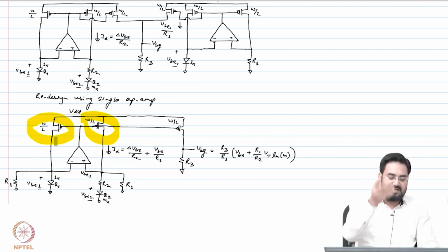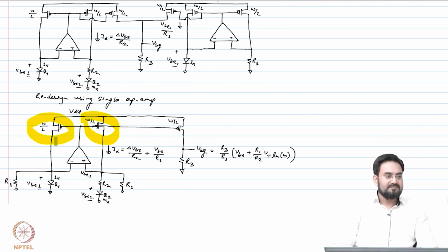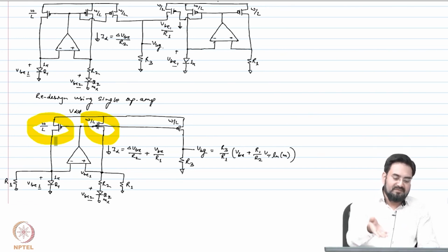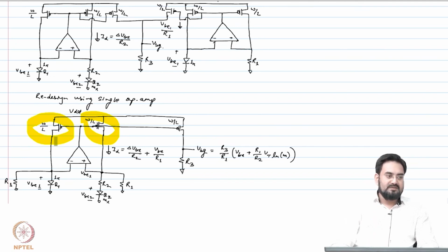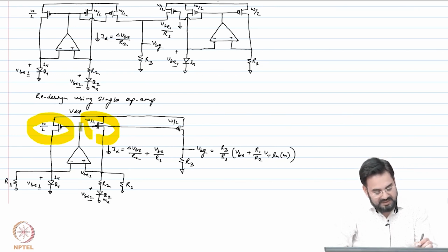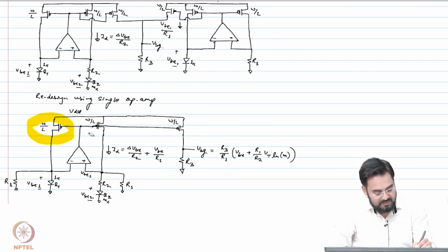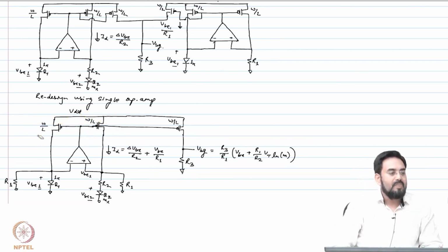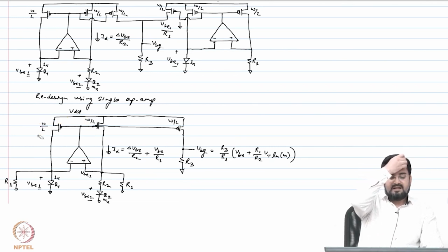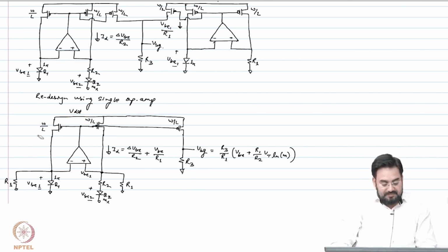Okay. So let us say you design it for 500 millivolt, then the VDS of this device will be much different compared to your VDS of the other two devices. Okay. So that is why inaccuracy here might be more compared to standard band gap. And other thing is, now you have to match these R1 also on both sides.